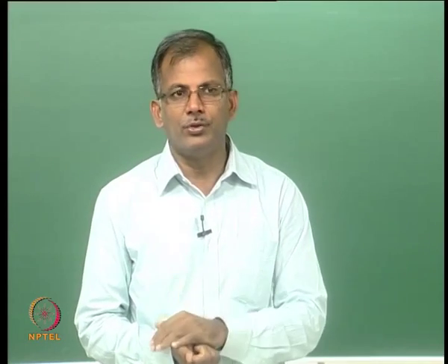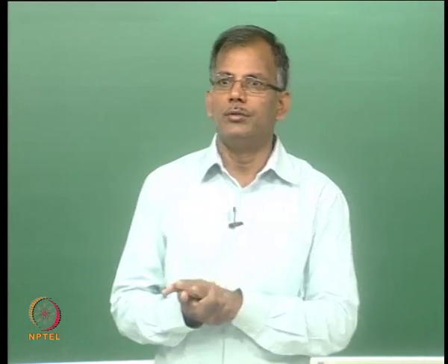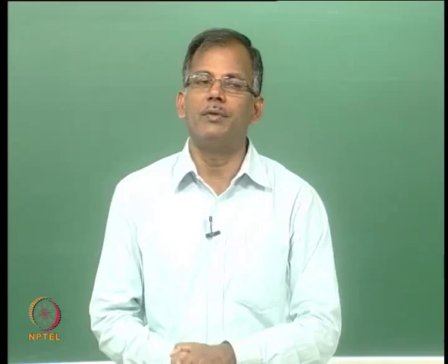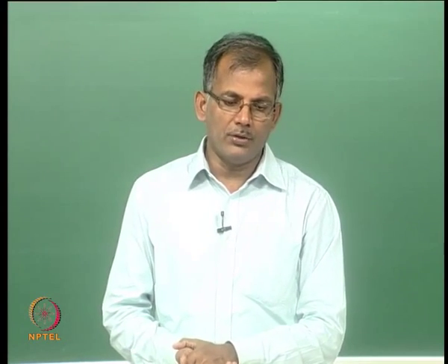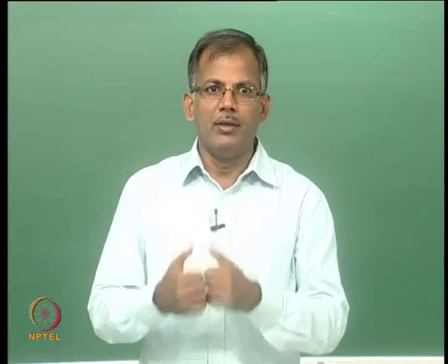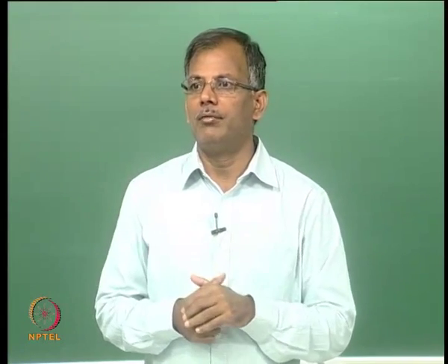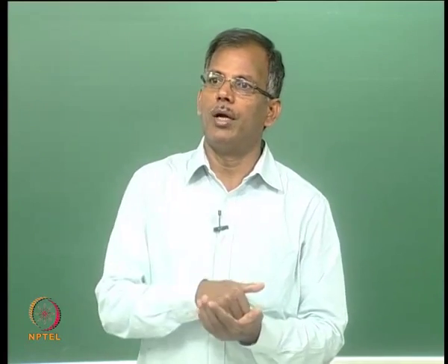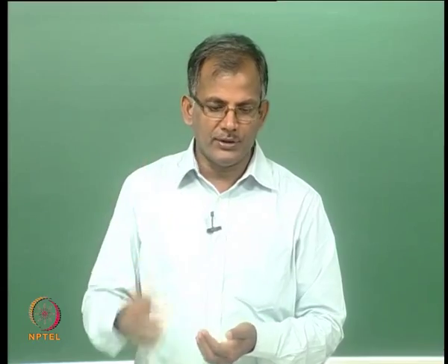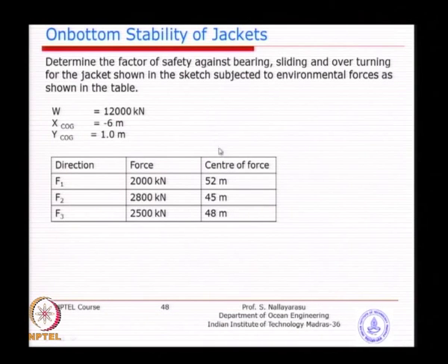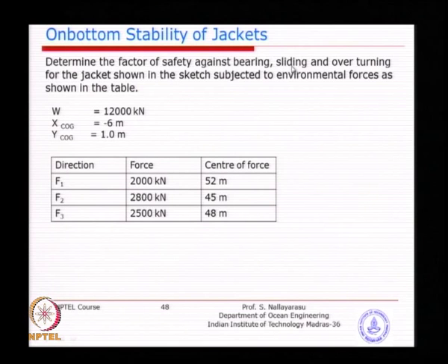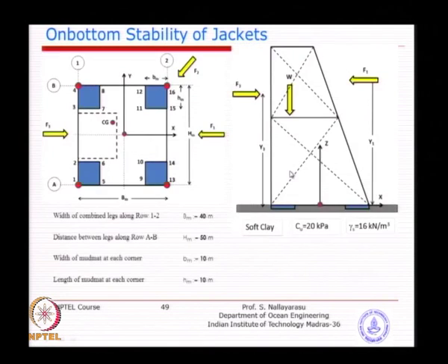But initial calculation of bearing capacity you should use d is equal to 0, because that is how we start with, and later if you are asked to find out the settlement, then use that as the depth of the foundation to go and increase your bearing capacity, which is the second step. Right now in this problem I have not asked you to go there, it is simply finding out the factor of safety against bearing, sliding and overturning.